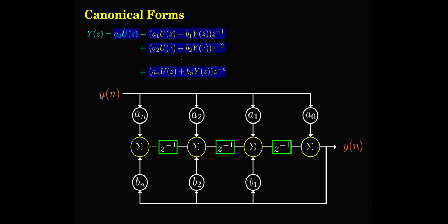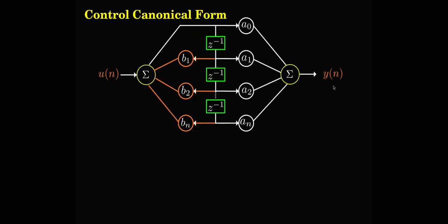Here it is not the control canonical form. Here if I observe the last state, this state is based on this state. This is another state. This is another state. This state will dictate this state, and from this state you can observe this state, and so on. You can cascade. From the last state you can observe all the information of the system. Therefore, it's called the observer canonical form, whatever you can observe at the output. So this will become a bit more clear if you write it in the state equation form. Let us do that.